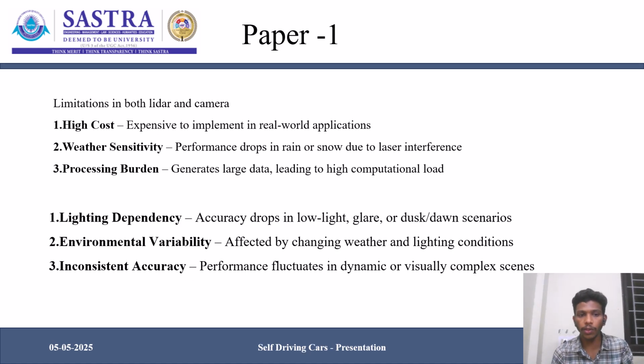When I talk about the limitations of both LiDAR and camera, LiDAR has high cost, weather sensitivity, and processing burden. It is expensive to implement in real-world applications. It has weather sensitivity that drops its performance in rain or snow conditions. And it needs a lot of data, a lot of computation power, and a lot of time to process all this data.